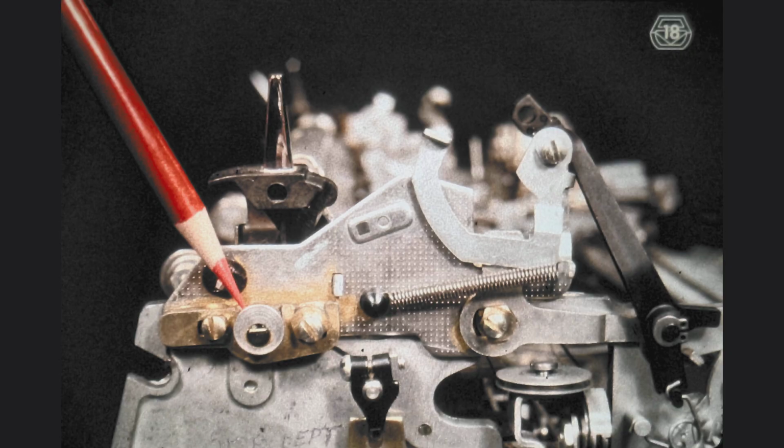The inclusion of the ABC lever, or multiple copy control lever, solves that problem. By changing the position of the ABC lever, we rotate the eccentric indicated by the red pencil, and, as a result, move the whole platen support frame forward or rearward. Take whatever time you need to examine this mechanism on your machine, and note that, with the exception of the ABC lever, you will find all of these platen support parts on both sides of the machine.